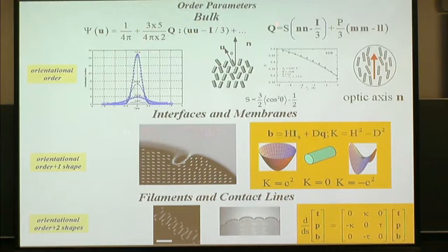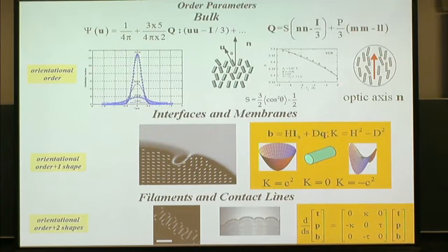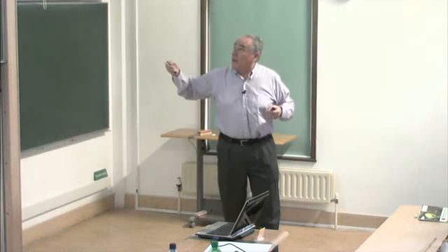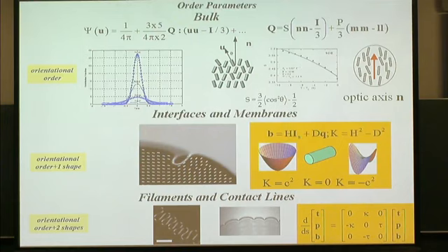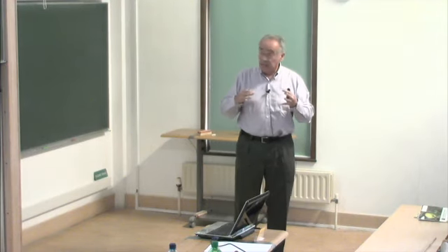One is the scalar part, which is the amount of orientation between the molecules and the so-called optic axis or average orientation. This variable for thermotropics is a function of temperature. As temperature increases, this order parameter decreases, or it is also a function of concentration. This is a nanoscale variable that is a fast, short length scale variable.